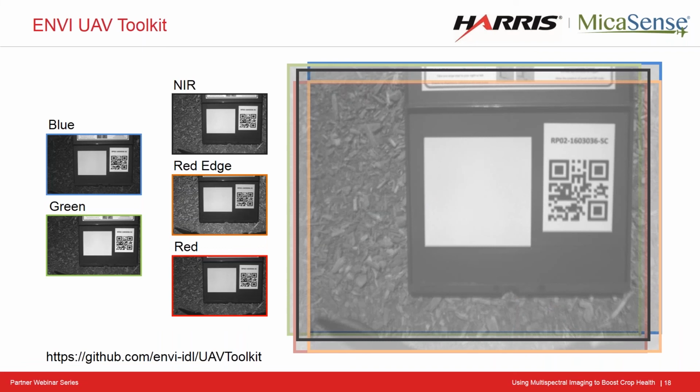All right, this is a visual of the UAV toolkit. So this is free software that we distribute through our GitHub account. And what this does is it does image-to-image alignment. So on the left-hand side of the screen, you can see the blue, green, near-infrared, RedEdge, and red frames. So these are the 5 frames that will come back from the MicaSense RedEdge camera. And then they all need to be co-registered or aligned to one another so that you get a final kind of image stack coming out of it.